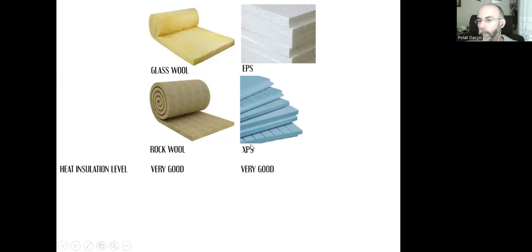Just like EPS and XPS, they provide a high level of heat insulation as well. Fire resistance, it's very good. They're inflammable, incombustible. But EPS and XPS are very bad. We shouldn't use them where there is a risk of fire. We shouldn't prefer them. Water resistance, these are bad.